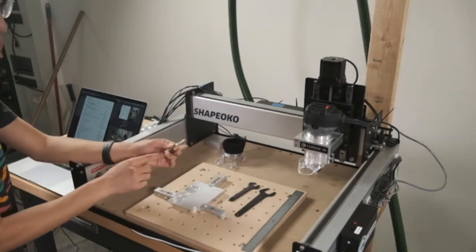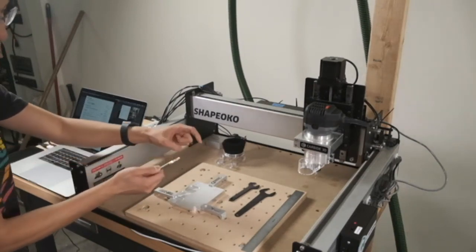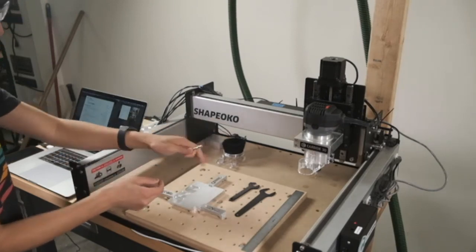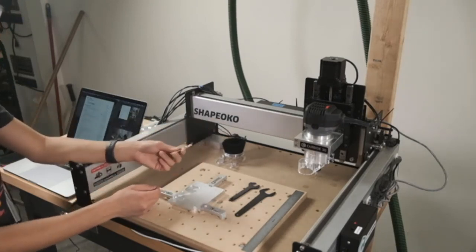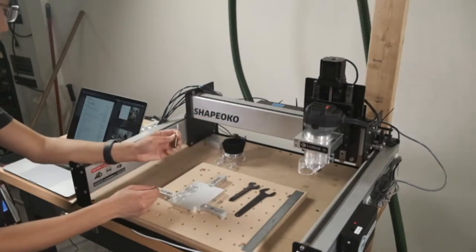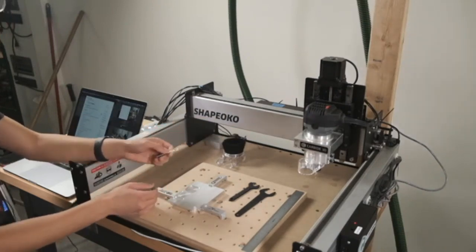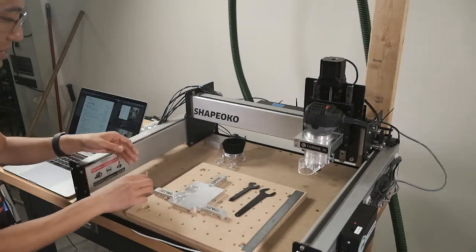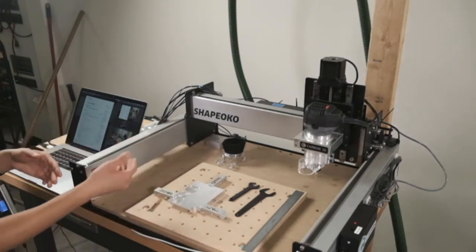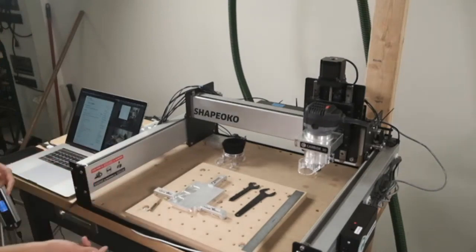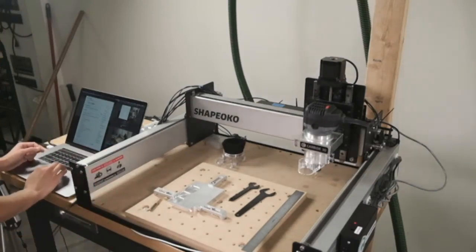Like a 1/4 inch extra long end mill, you probably won't break with a Shapeoko. 1/8 inch is definitely in the realm of tool breakage. But for tools like that, you would want to back off on your speeds and feeds, let's say 20% or more, but it's a decision you'll have to make as you go through things. All right, so that is travel versus clearance. We have first 5 items checked off.